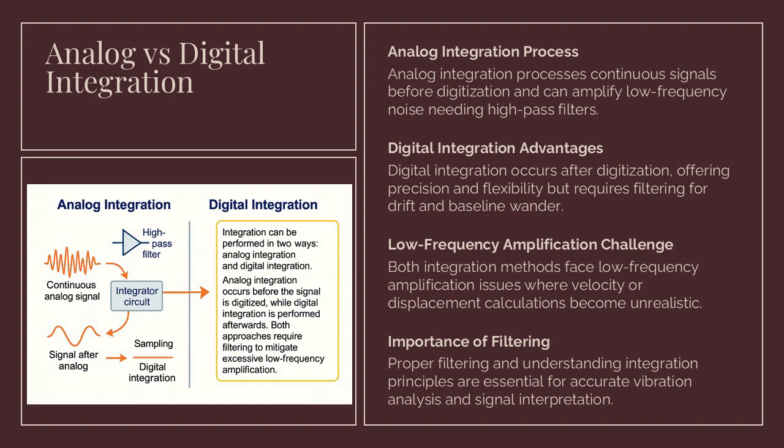Digital integration, on the other hand, is performed after the signal has been sampled and digitized. While digital integration offers more flexibility and precision, it still requires filtering to avoid issues such as drift and baseline wander. Both methods share the challenge of low-frequency amplification because integration mathematically divides by frequency. As frequency approaches zero, the calculated velocity or displacement approaches infinity, which is unrealistic and problematic. Therefore, proper filtering and understanding of integration principles are essential for accurate vibration analysis.